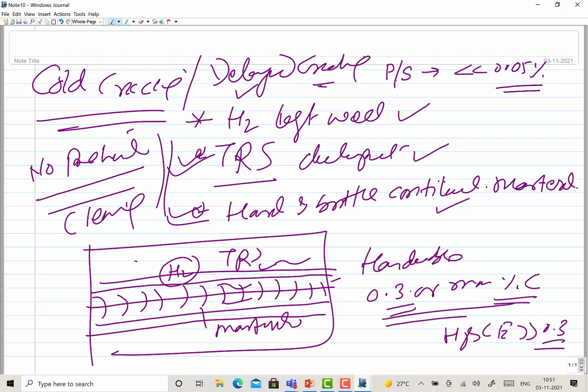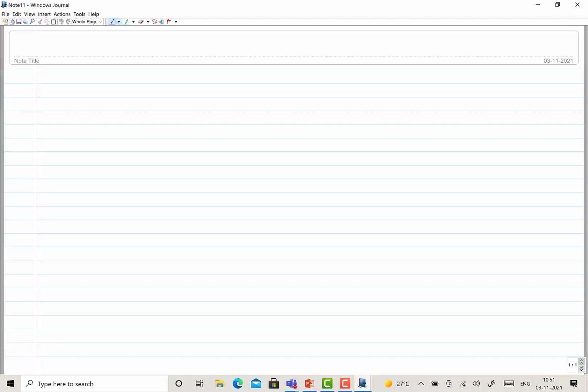It doesn't happen immediately after the welding. It may take maybe 24 hours, maybe 7 weeks, maybe 15 days, maybe 6 months. So that's why we call it a delayed crack as well. And it's happening primarily due to the hydrogen, tensile residual stress, and hard and brittle martensite transformation. So what can we do?